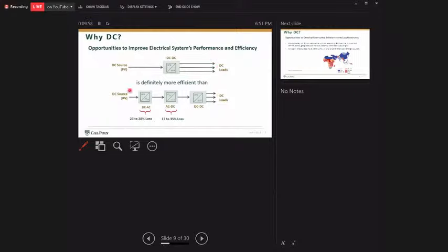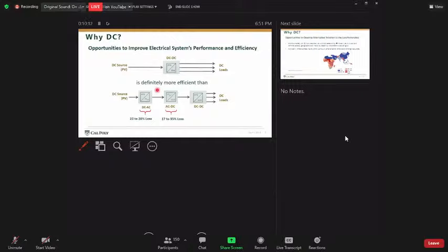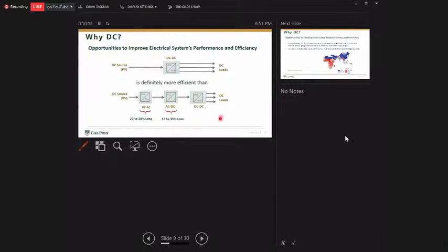What we have right now is, as some of you know, from the solar panel, we invert it to AC, to be able to connect to our house. And then right at the point of connection to the loads, we convert that AC back to DC, and then another DC to DC. In the process, you're going to have more losses. Not good. Very lossy, it's not efficient.